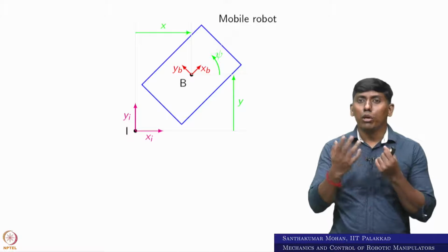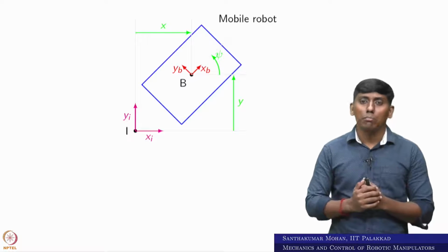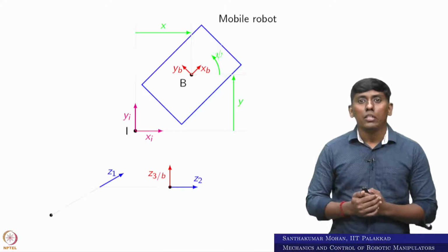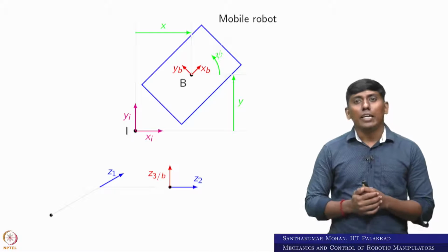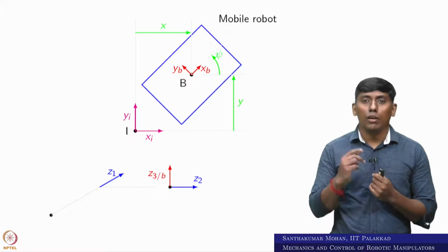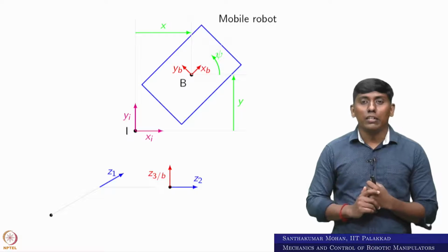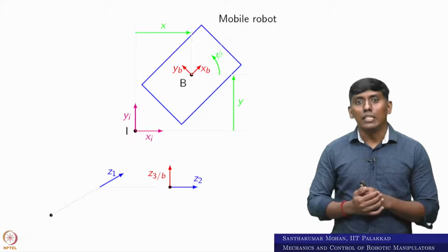So now we want to write this in the Denavit-Hartenberg approach. For that, first we have to draw the frame arrangement. So how can we do the frame arrangement? I can see that there are 2 translations and 1 rotation. So, in order to make life easy, I assume